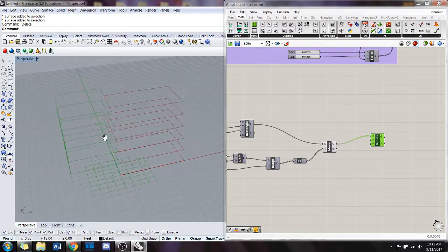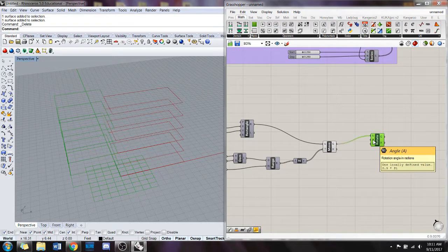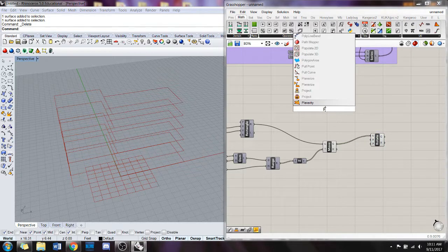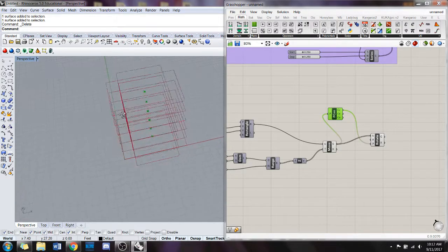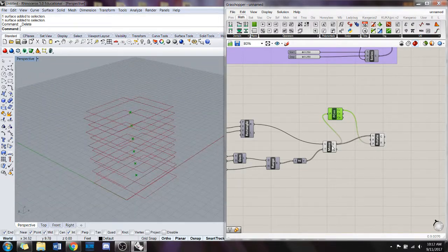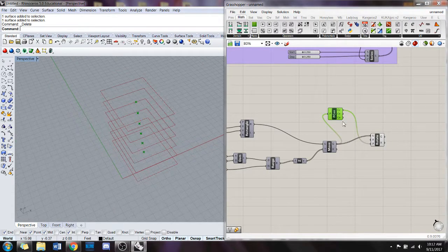And see, now you've got this rotation. It's going to default to rotating by 1/2 pi, which is 90 degrees in radians. And it's going to default to rotating in XY, which is fine, but we can also use a polygon center again to find the center of our polygons. And we can use that as our base rotation, so it rotates without moving about the center of each polygon. We've rotated everything, but what if we want to rotate them parametrically?